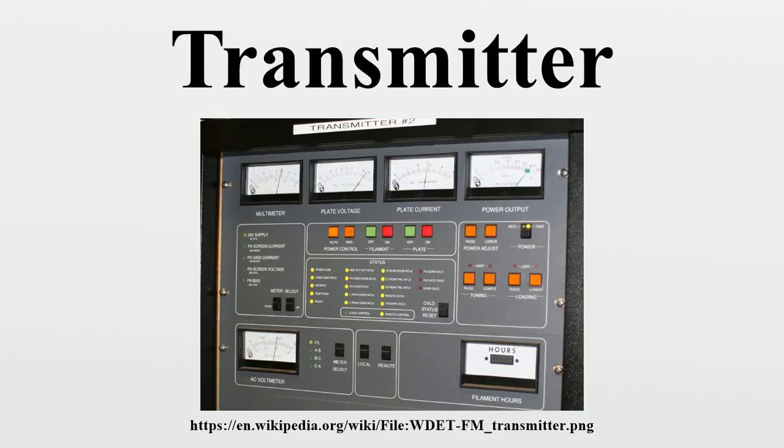A practical radio transmitter usually consists of these parts: a power supply circuit to transform the input electrical power to the higher voltages needed to produce the required power output, and an electronic oscillator circuit to generate the radio frequency signal. This usually generates a sine wave of constant amplitude, often called the carrier wave, because it serves to carry the information through space. In most modern transmitters, this is a crystal oscillator in which the frequency is precisely controlled by the vibrations of a quartz crystal.